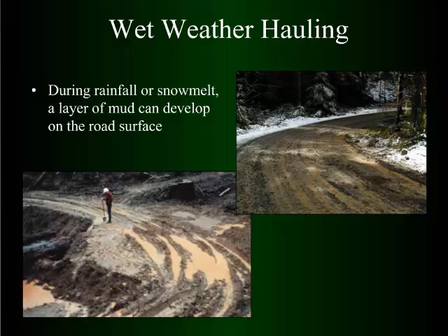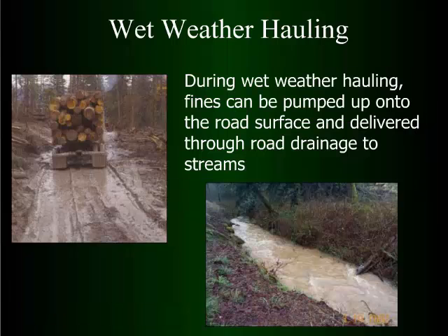The situation where you're getting the pumping action here, either this road doesn't have enough rock on it, or it may at this point have no rock on it, but it probably has had enough moisture in the subgrade that you're seeing the pumping action here. A case where a geotextile and a lift of rock over it might fix the problem. This is a situation where the road's pumping mud through, and you can see it in the water there. That's primarily sediment from a logging road that's going down that waterway there.